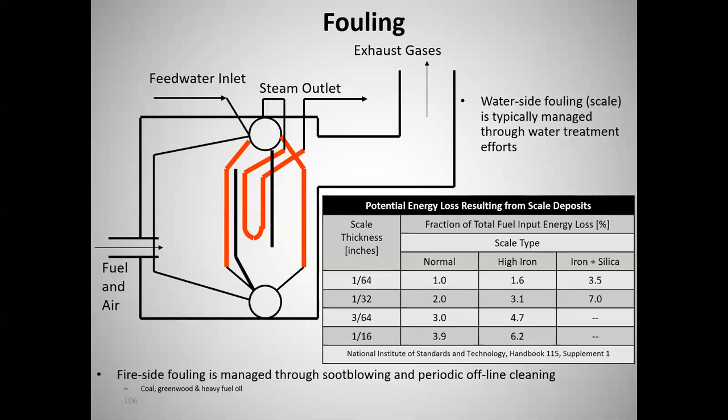That's another problem. Because see, it's the water that cools the boiler tubes. Now, boiler guys, they don't really care much about efficiency, but they care a lot about not melting their boiler. They care a whole lot about that. Because if you melt the boiler, you damage the tubes. Then you have to come down, identify the tubes, go in, cut them out, and repair them or replace them.